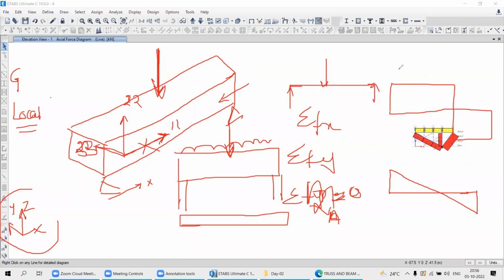It means that over the support, your shear force is very, very large. Due to this very large intensity of the shear force, there will be the possibility of development of shear cracks in this direction. So what I would like to discuss is that the shear force is developing over the depth of your member. So your depth axis 2-2 is there.